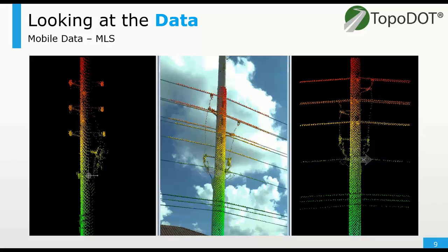So generally, MLS and TLS or any terrestrial data is going to be better quality, more detail than an airborne system, which is going to be necessary in order to extract what we see here today, or most of it, as well as all the features mentioned in the previous slide. But with that said, airborne data still plays a role when focusing on larger features, specifically transmission lines.